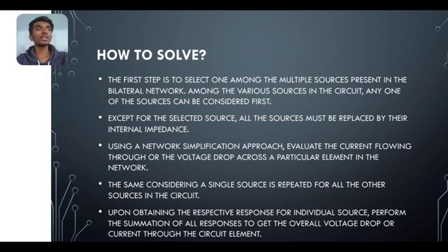Upon obtaining the respective responses for individual sources, perform the summation of all responses to get the overall voltage drop or current through the element.